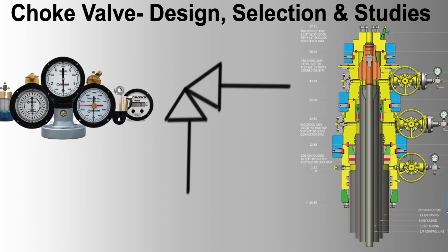Instrumentation and control devices. 1. Actuators. Type: choose between pneumatic, hydraulic, or electric actuators based on application requirements. Control: ensure actuators can precisely control the valve position for accurate flow and pressure regulation. 2. Sensors. Pressure sensors: high-precision sensors to provide real-time pressure data upstream and downstream of the valve. Position sensors monitor valve position to ensure accurate control and feedback to the control system.